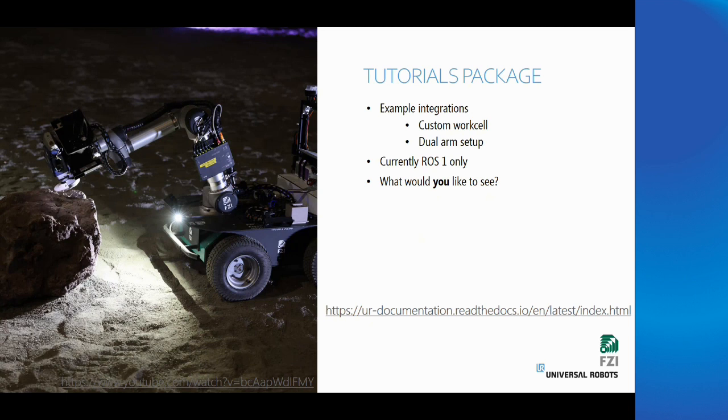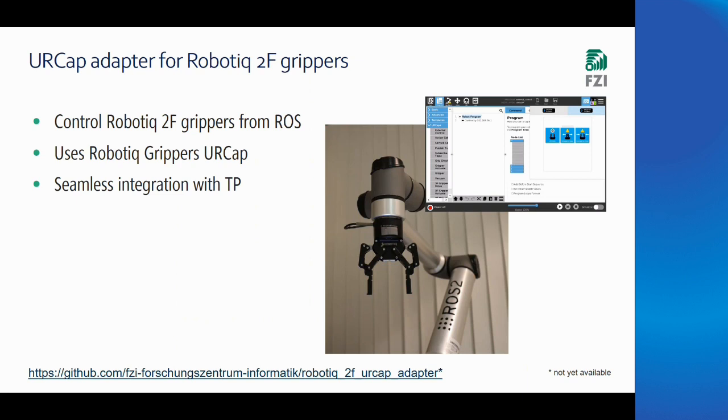One other thing we at FZI have been working on recently, just to disclaim, this is work from FZI, nothing to do with Universal Robots. We have the problem that in ROS2 especially, we had trouble interfacing Robotiq two-finger grippers. There seems to be no real ROS2 driver available at the moment. However, there's a really nice URCap that you can activate on the teach panel, and the nice thing is this URCap also exposes a socket interface to the outside world.